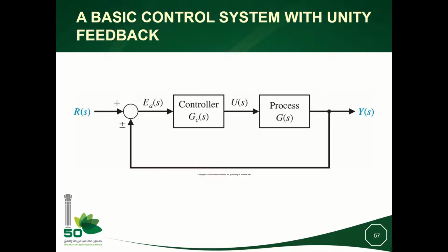This system is known in the literature to be a system in feedback form, because we are feeding the system input by something related to the output. Okay, so here generally we have some transfer function that is characterizing the control action, and here we have our basic process or system, which is given by G(s). Now, these two subsystems we can replace by one block, which is GC times G. Okay, and here we have a unity feedback.